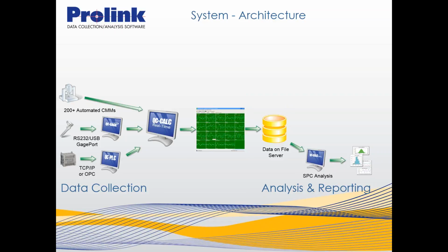There is another function. QC Calc SPC can also operate in a remote monitoring mode. So you could be sitting here at your desk, flip it into monitor mode, and look at any one of these copies of QC Calc Real-Time on the shop floor and see the data in real time in the same way that the operator does. So that's another function that it has.